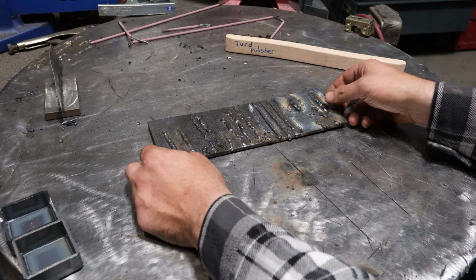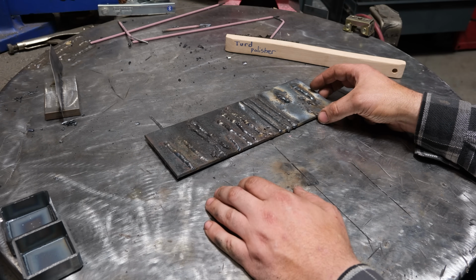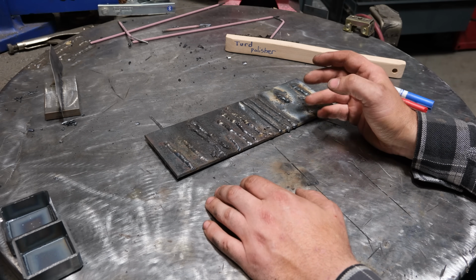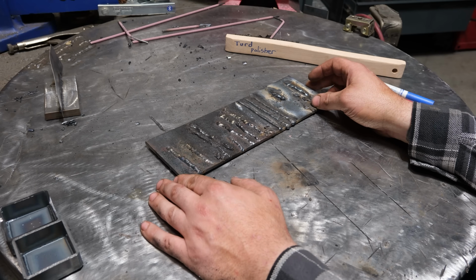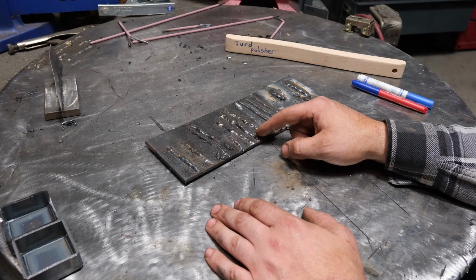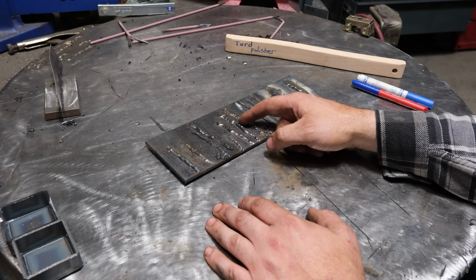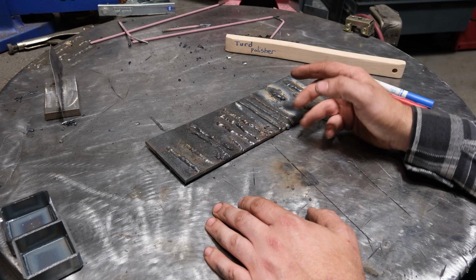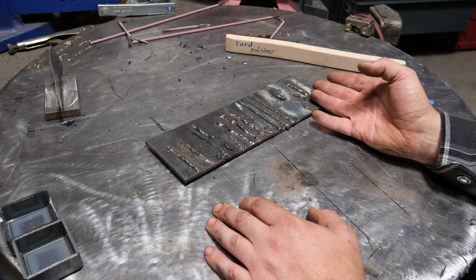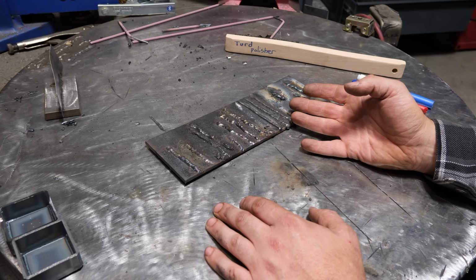And I got this here. I don't know where this came from or who was practicing on it, but this is pretty atrocious. It came out of a scrap bin. And I was looking here, and this appears to be all stick welds. There's porosity, cold beads. It's pretty evident when you look at this that there's a lot of defects here, right?